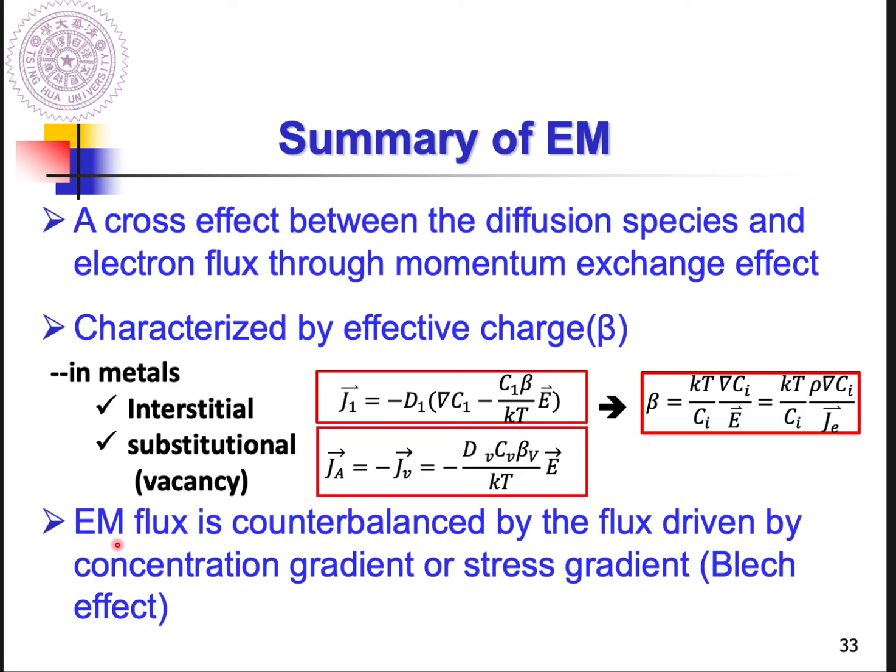So are there any driving forces that can counterbalance the atomic flux driven by the EM, or driven by the electrical field? Yes. The first one is the concentration gradient, right? And the second one is the stress gradient.